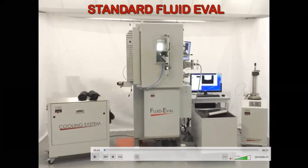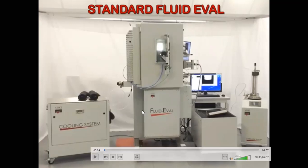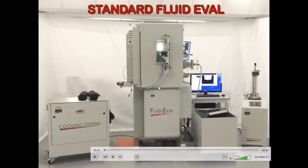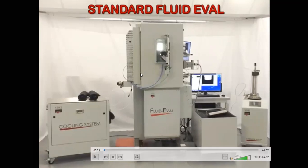So what I was saying is that this equipment is available in reservoir fluid labs, and the name of this equipment is the PVT. The job of the PVT is to find out the bubble point pressure, and we do the differential liberation test with it. We find out the content of asphaltene using this equipment, and we do a swelling test. So we do a number of tests using this equipment. Mainly for the bubble point pressure, this equipment is used to find out at what pressure the first drop of gas comes out of it.